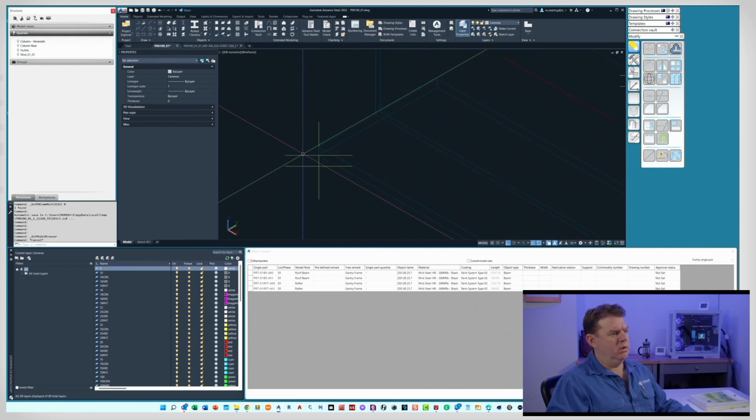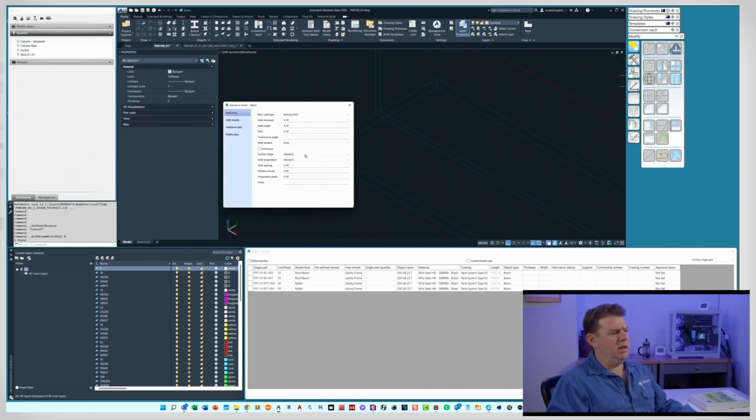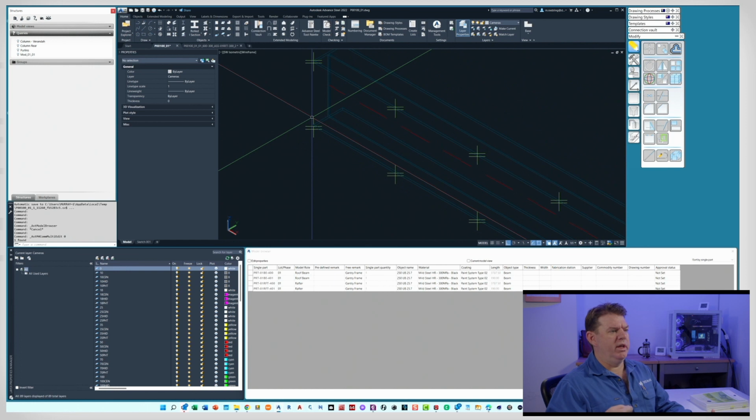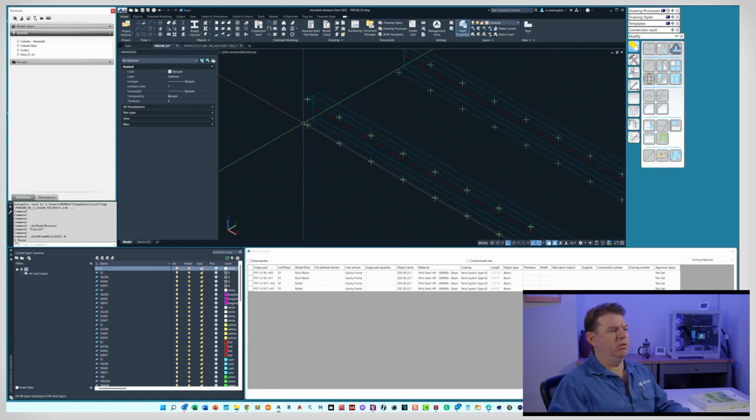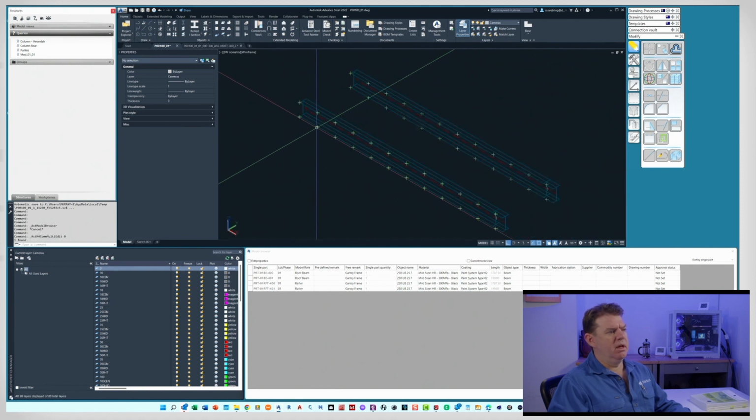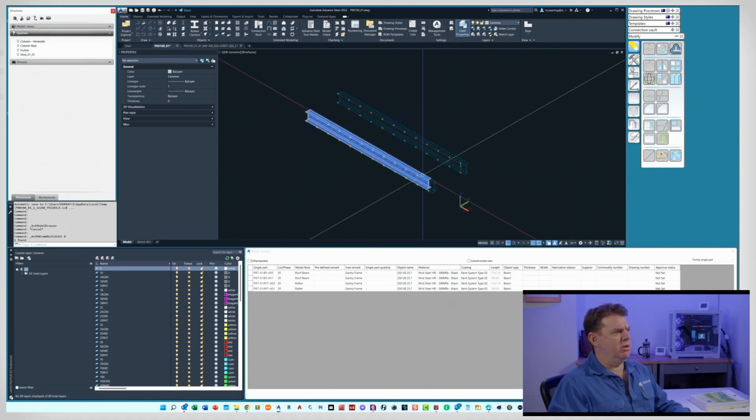So I will come down here. This is a backing weld, and we've got a backing weld on both sides here, so it's a double weld. And I've put the style of weld that it is in the additional information, so it will show up on the assembly drawing, so I can double check to make sure that all the weld symbols are matching up to the correct symbols and shapes. So this is how I've done it to do a check.